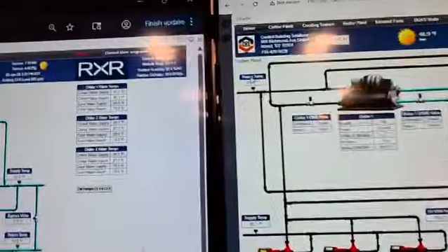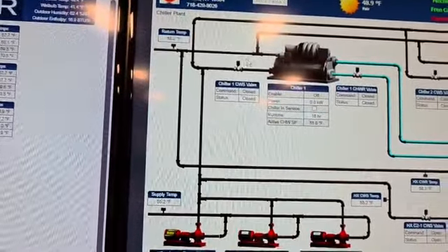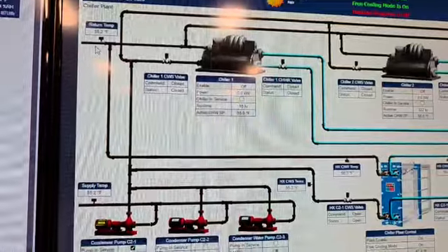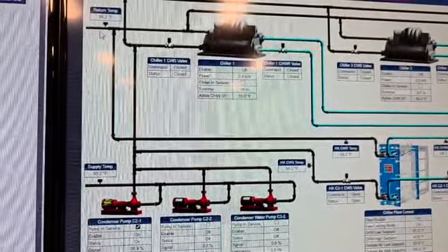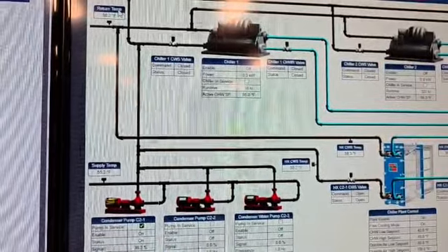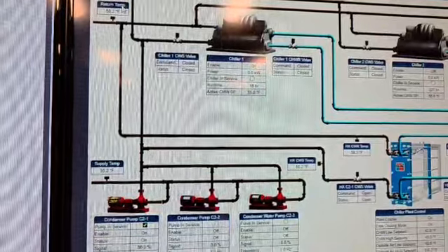You have your return temperature. You have to be careful with this because people say return to the unit or return to the tower, right? You need to understand how the system has been built and the terminology that they're using. Sometimes they say, oh, the return water, return to where? Return to the building or return to the tower, right?